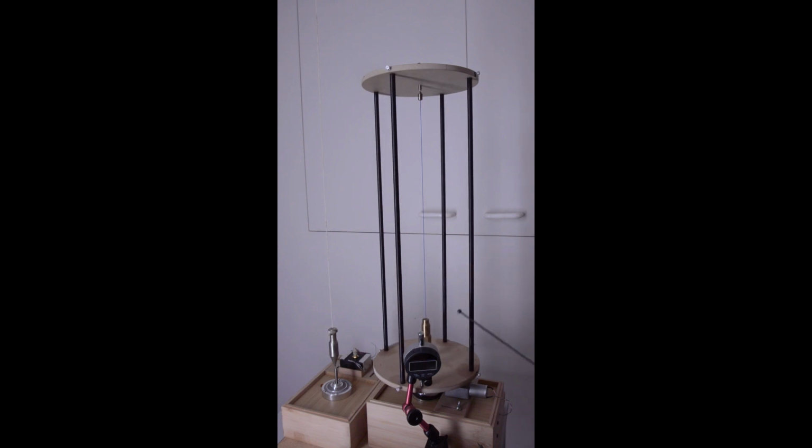And as I mentioned, the error between the centre shaft, the vertical shaft, and this mounting disc which holds these struts is 1 millimetre. However, over this distance of 400 millimetres, it gets amplified to about 20 millimetres. Now, therein lies the problem. I don't know of a house that is that accurate with a floor and roof ceiling less than 1 millimetre in concentricity. So, you know, what's going on here?